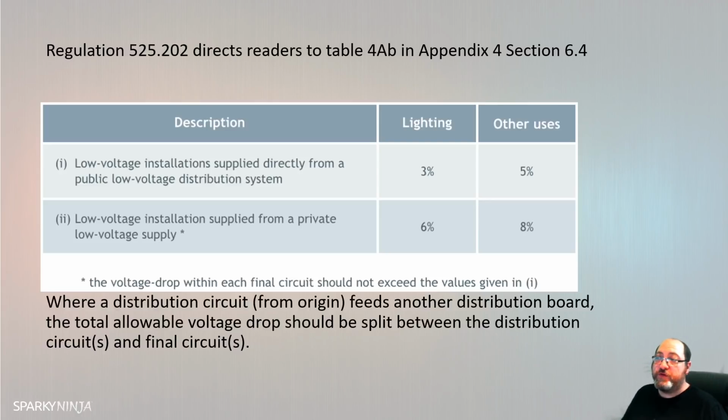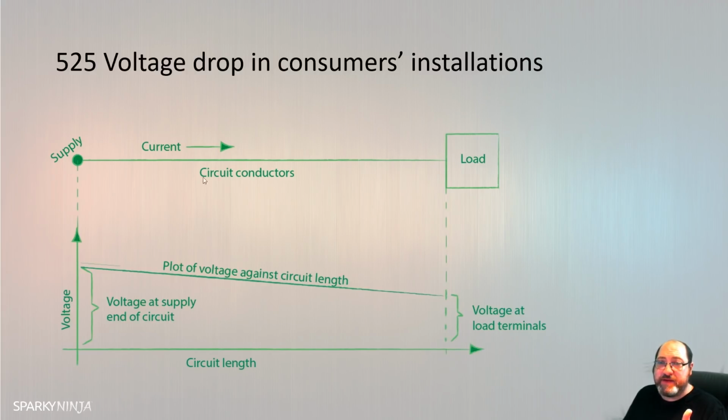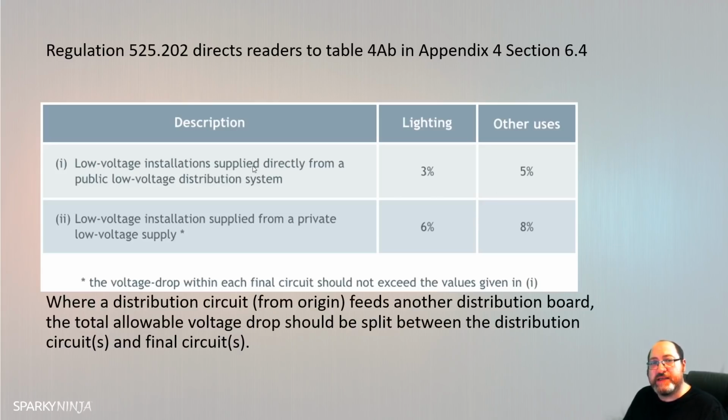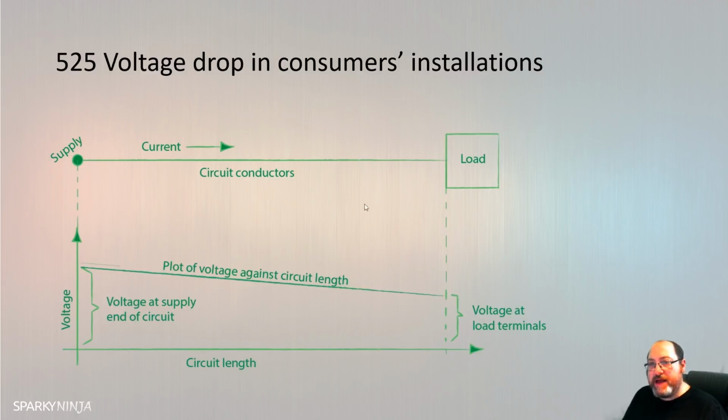So we need to do the volt drop calculation whenever we do a cable size selection. The last step is to verify the volt drop, and what we compare it to is these maximums. So 5%, 3%. But bearing that in mind, when we do things like a sub main, let's say there's another fuse board here, the cable feeding this must be of low volt drop to allow some leftover volt drop for the cable being connected to that board.